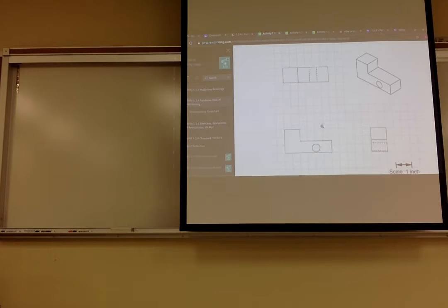Then what I'm going to recommend is draw on top of here and draw the first cutout you do. Right, this big rectangular cutout. How big is it? Well, it's 2 by 2.5. So you draw a rectangle from this corner by 2.5 by 2. And then you're going to cut it down 1/2 inch.